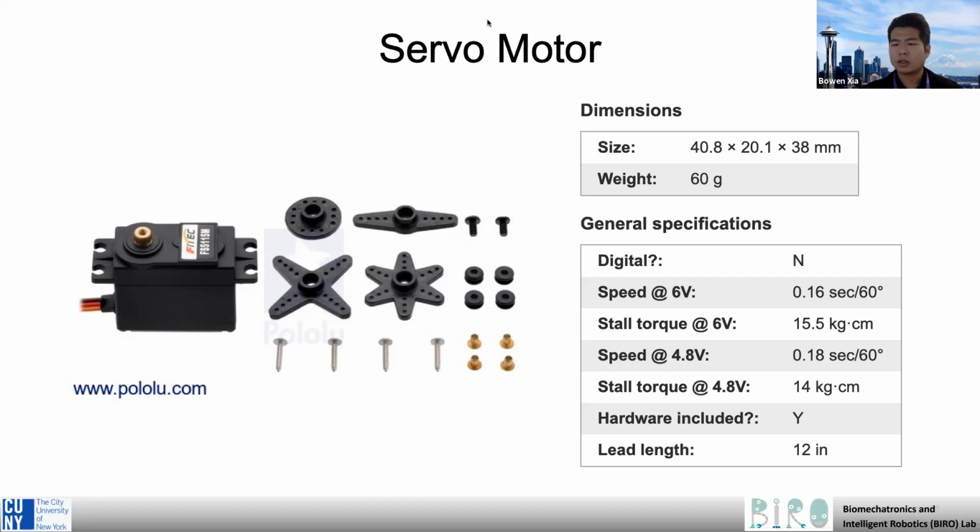When the command is sent through this control wire, the desired angle is encoded using pulse width modulation, PWM. In PWM encoding, the desired angle of the motor is proportional to the width, which is the duration of an electric pulse that is sent to the servo motor on the control wire. This signal is sent at regular time intervals to keep the motor at the desired angle.